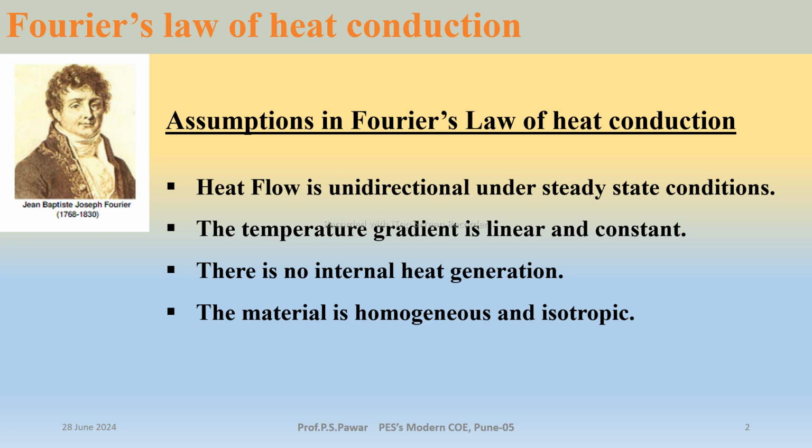Steady state means the temperature will not change with respect to time, that is the steady state condition. And an isotropic material means properties will remain the same in all directions of the material. So these are the basic assumptions while deriving Fourier's law of heat conduction.